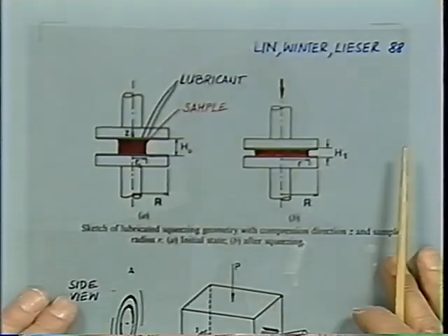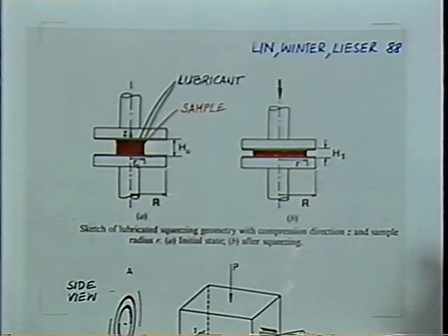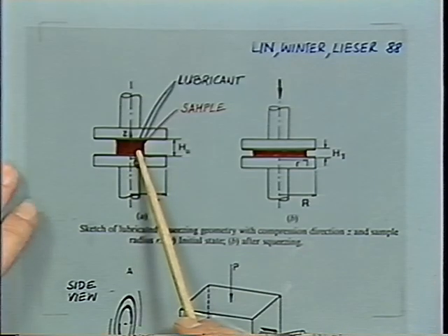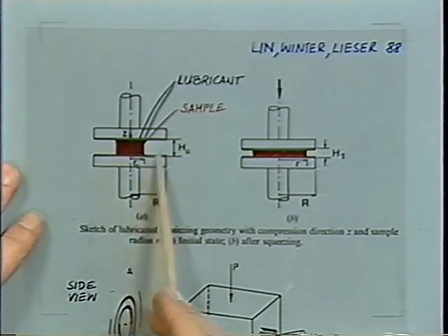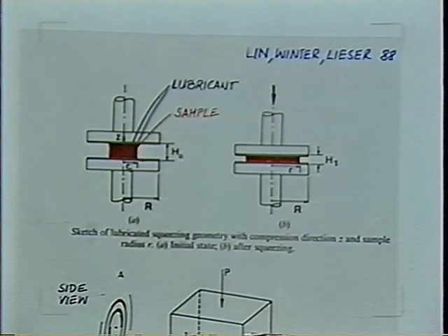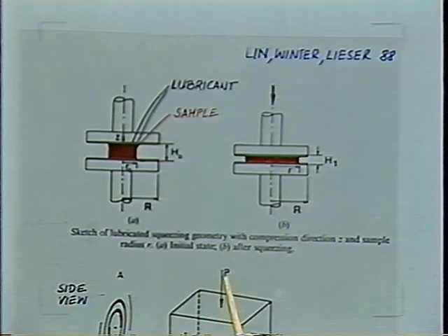Let's go to a completely different experiment, and then that would finish up the rheology. The large strain behavior in extension is also very interesting. We exposed the sample to equibiaxial extension by lubricating the surface of the squeezing apparatus. This experiment can be performed at very high temperatures, this lubricated squeezing experiment.